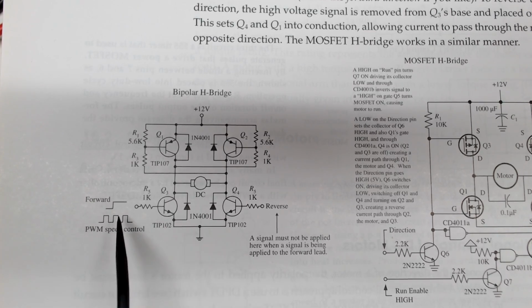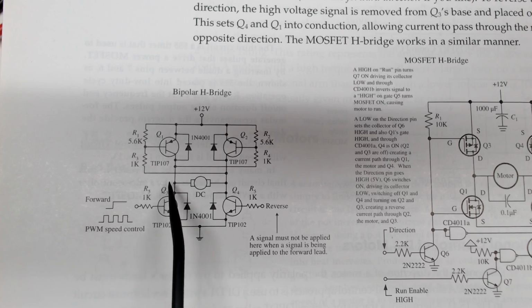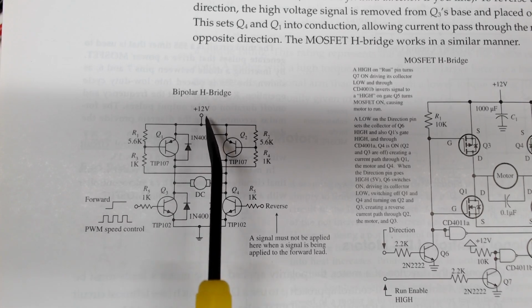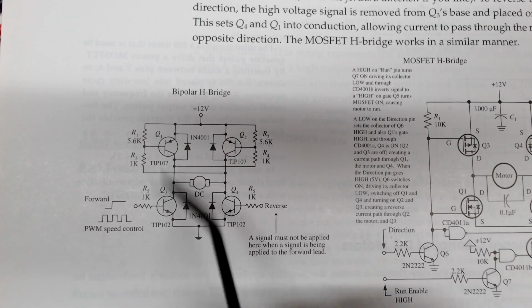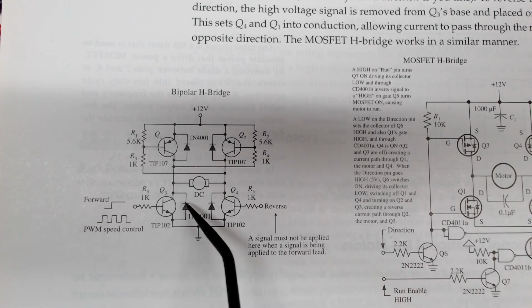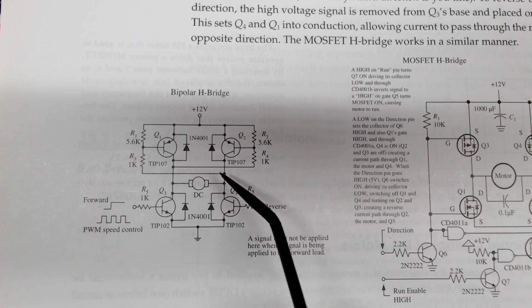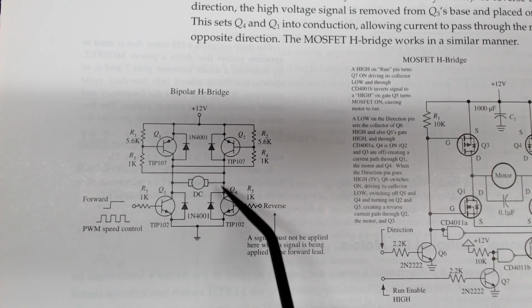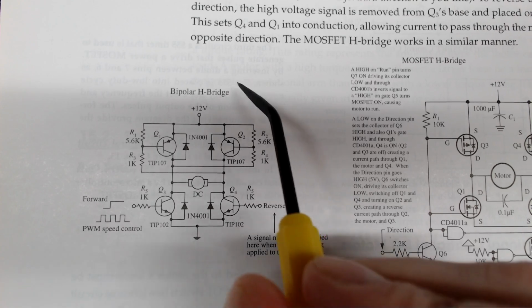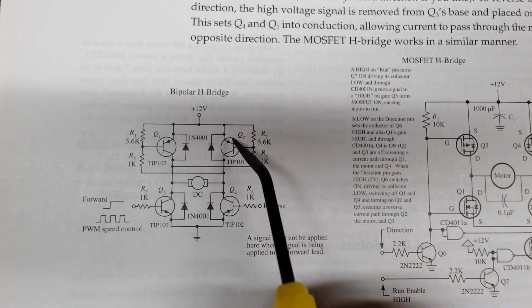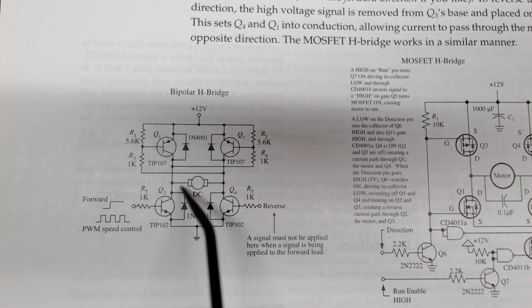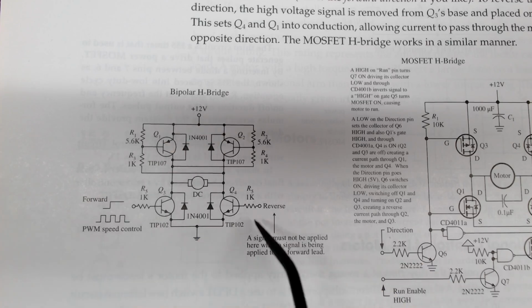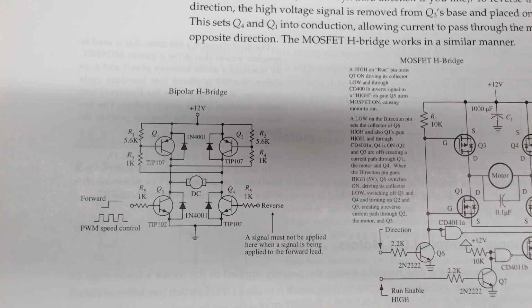Basically what happens is we bias this transistor, which allows this to flow through this collector. In this case, I have a 12 volt supply. The supply doesn't matter overly in this case. You have to tweak these values, of course, but it doesn't matter overly. This allows power to flow through this motor. In particular, it goes through this PNP and this NPN, right? So it's going to do this sort of thing. And it does the reverse over here if you put a reverse voltage here. So it allows the motor to turn in both directions using these voltages.